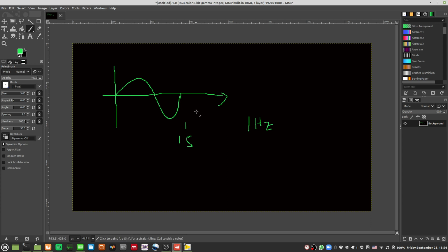Okay, so if your sampling frequency is 1 Hertz, what are you gonna get? Let's say you sample this waveform, right? And then you wait 1 full period before you sample again. So what is your bar chart gonna look like? Your bar chart is gonna look like one flat line here, right? One flat line here. And if you keep going the same way, it's going to look like a flat line throughout. So what's the minimum frequency you need to pick up all these waves?